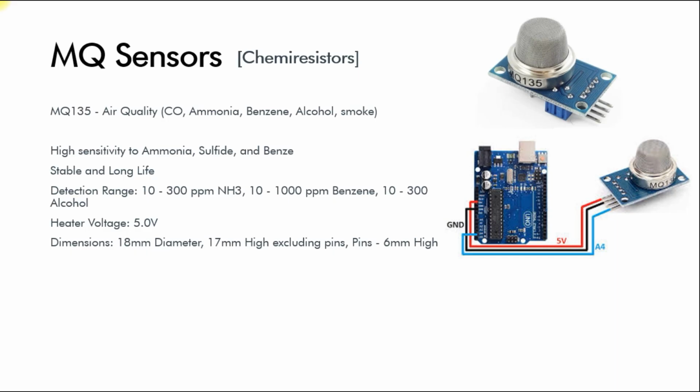After watching the gas levels, I will decide whether I need to alert the systems or inform somebody. I can take the necessary action after watching the sensor values. If you want to perform this task, you have to read the analog pin. So I'm connecting VCC and ground to the power supply pins of the Arduino board, and I'm connecting the analog output pin to my A4 pin, that is an analog pin.